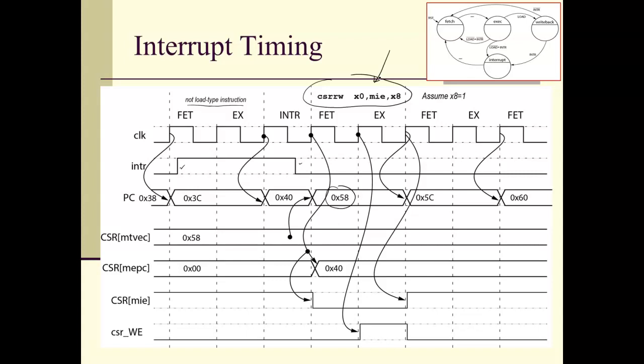So that means the first instruction in the interrupt service routine, I re-enable interrupts, which means I'm going to turn the CSR write signal on down here, and that's going to write that value into the register. So life is good on that one. The result is, remember the interrupts are disabled automatically in hardware. This instruction re-enables them. So you can see that pulse width is going to be 2 clock cycles long. And so that's the answer to our first question.